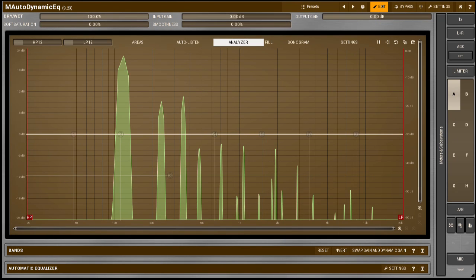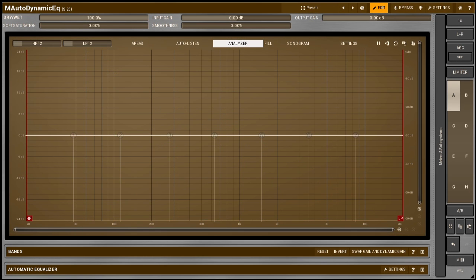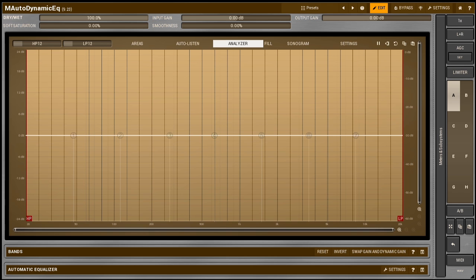You see, the FFT analyzer shows true amplitudes of signals. It's useful information for mathematical analysis, but again, it doesn't correlate with the way our auditory system assesses the loudness. The power of the signal in frequency bands is much more useful to this purpose. In the past, mixing engineers used analog analyzers in which the 20 Hz to 20 kHz range was split into 31 sub-ranges, each of 1/3 octave bandwidth.